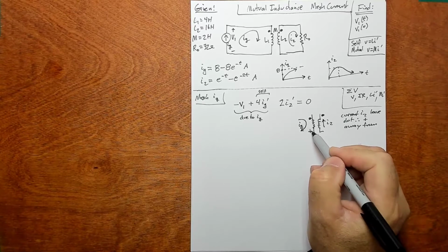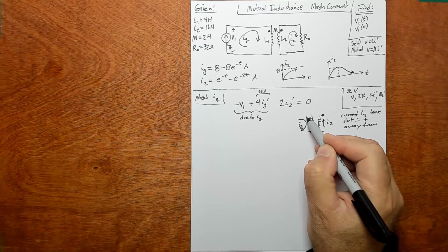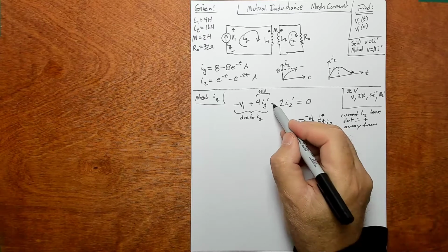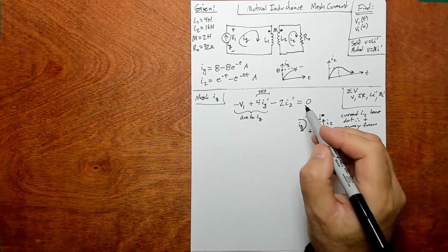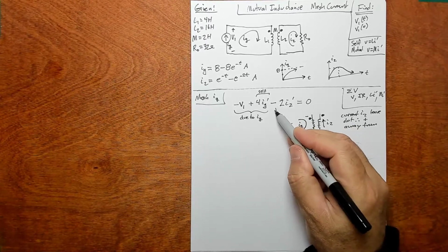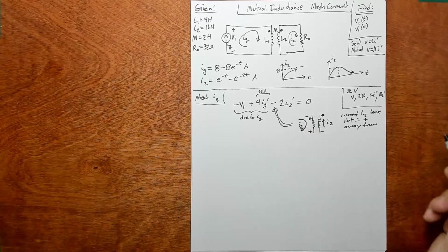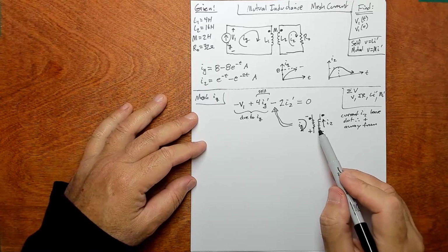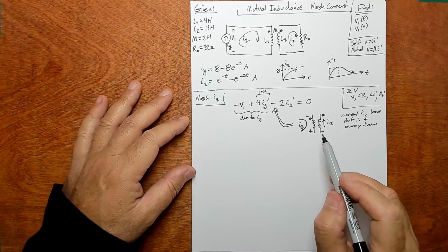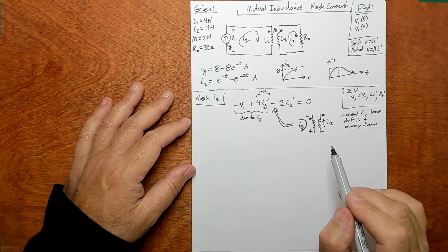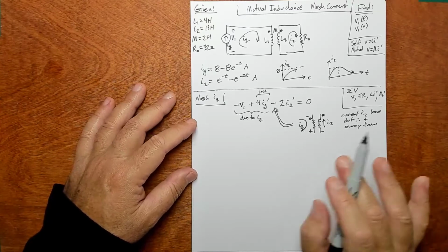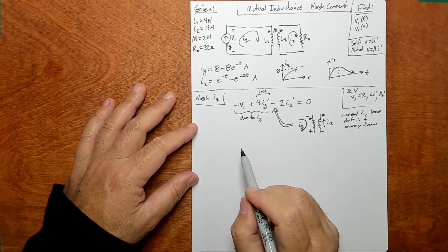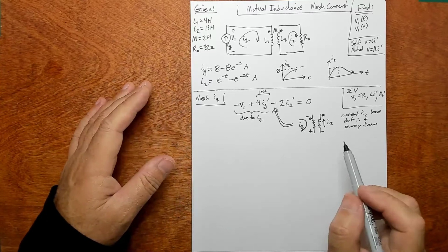This away from the dot means we're coming into a negative sign basically. So this term is negative. Okay, so that's why this thing is negative. You've got to apply the dot convention for voltage, which is what I just did, and don't confuse that with the dot convention for energy, which is a totally different thing. Okay, that's that guy.